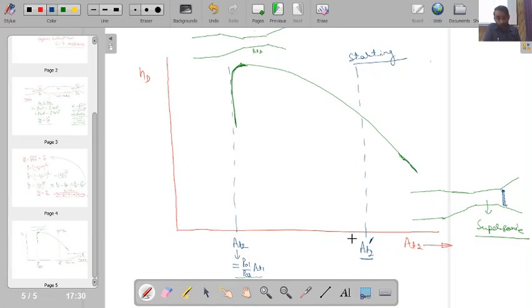Okay, so now when you are designing a diffuser, you will be able to design for maximum efficiency only if the operation of the diffuser is starting. Okay, so ultimately we design the diffuser for area A2 dash, so that our operation can occur. So the initial transient shock wave can go out of the system, and then we should be able to achieve the desired steady operation.